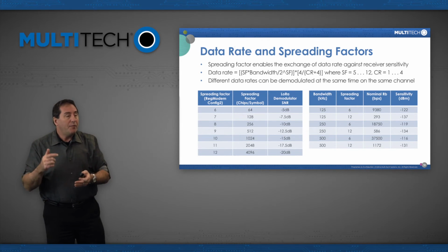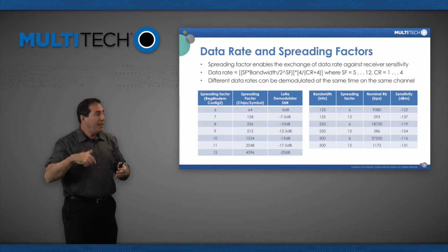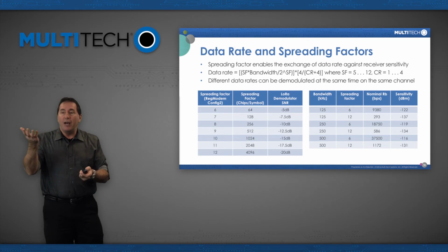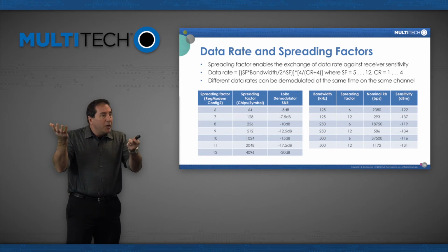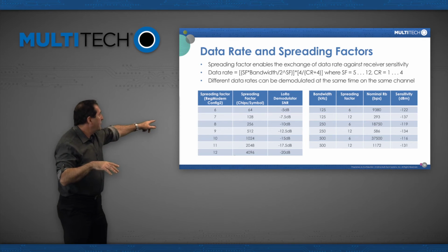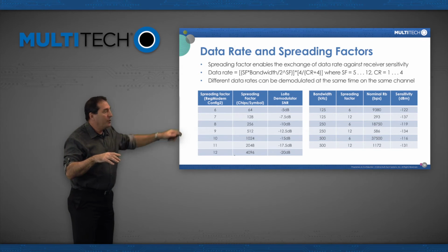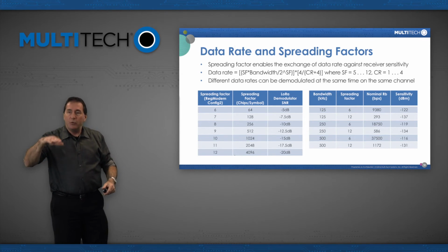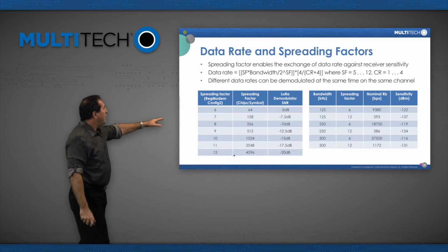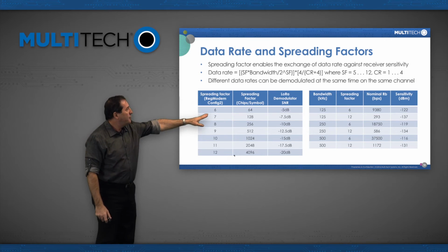And that's why we use a thing called automatic data rate in the LoRaWAN protocol to say, look, we always want to have the highest bit rate we can, but if you can't operate it reliably at a spreading factor of 7 and a certain bandwidth, we'll adjust that to where we can have a reliable signal, and then that's the data rate. So the data rate comes from the spreading factor and the bandwidth.